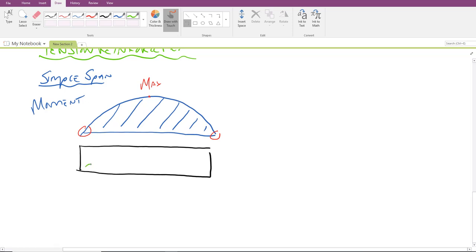What that means is that we need to have our rebar at the bottom edge where with positive bending, I actually think I said negative bending earlier. It should be positive bending. Positive bending will cause tension in the bottom of the beam because of the way it sags. The bottom of the beam will go into tension, so we need to make sure that our rebar is in the bottom of the beam in the tension zone.